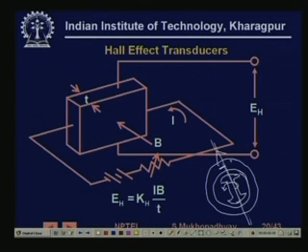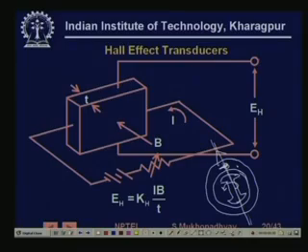So whenever this rotor comes to this position where the Hall effect sensor is placed, the Hall effect sensor will immediately sense that magnetic field. There is already current passing through it. The moment this rotor passes through that position, which is very small, for a brief time there will be a flux passing through the Hall effect sensor, and for a brief period of time it will give a voltage pulse.